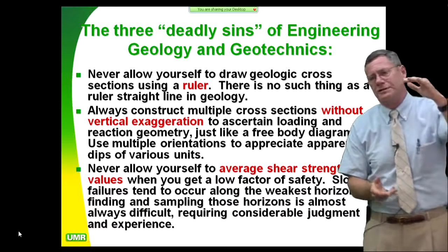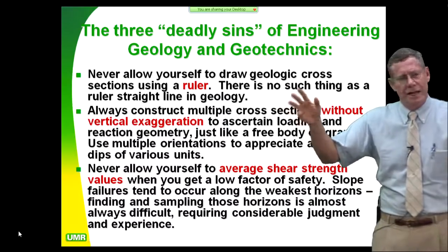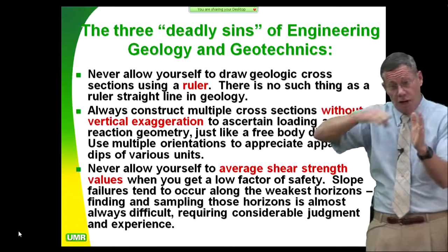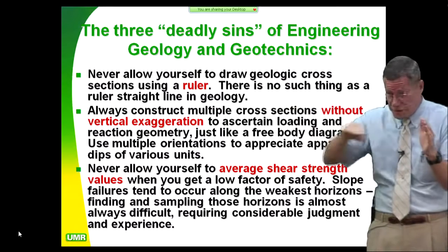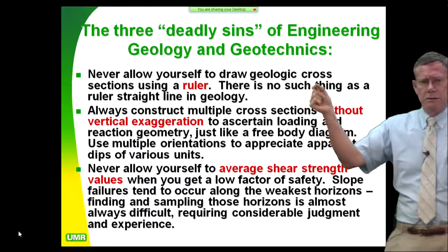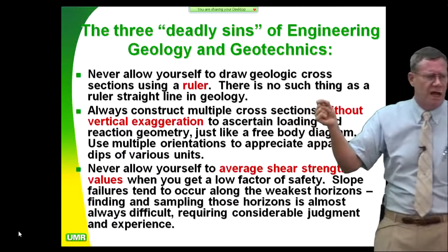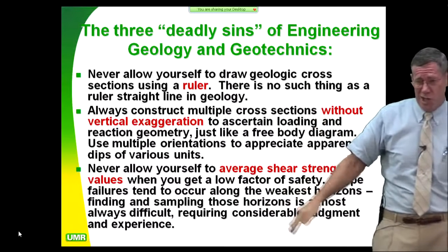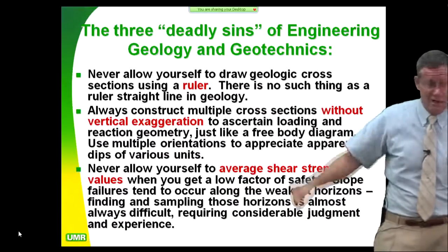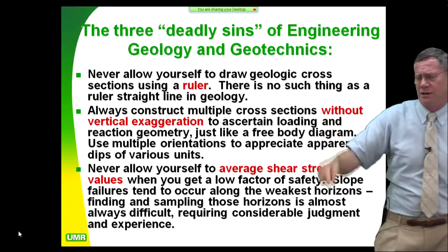If you had a 3-to-1 vertical exaggeration and you divide everything by 3, you're not seeing it like it really is. You need to draw the passive wedge, the log spiral shape of it, the Coulomb solution. You need to draw the active wedge to see where they are physically. This becomes of critical import when you start designing stuff next to channels and on hillsides. Because what you're going to find out real fast is you don't got the wedge out there you thought you had. You got water or air. And that's where you get into trouble.